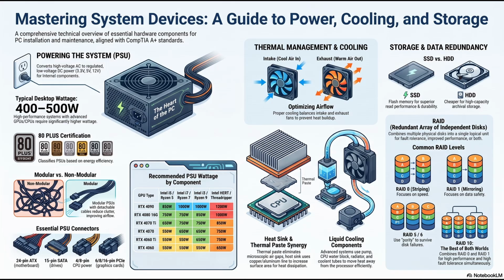And finally, the technology that feels like a nostalgic relic but still holds a vital place in certain industries: optical drives, the CD, the DVD, and the Blu-ray. Optical media is fascinating because it abandons magnetic fields and trapped electrons entirely. It relies on physical topography and the behavior of light. How does a laser beam read a movie off a piece of plastic? During manufacturing, a high-precision press stamps billions of microscopic physical divots, called pits, into a layer of reflective polycarbonate. The flat areas between the pits are called lands.